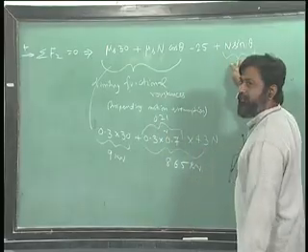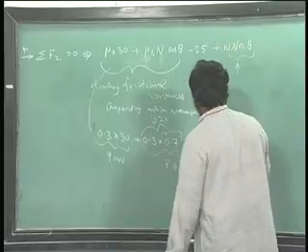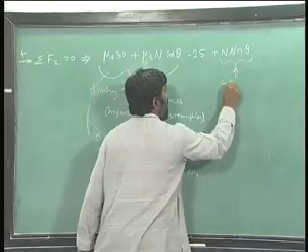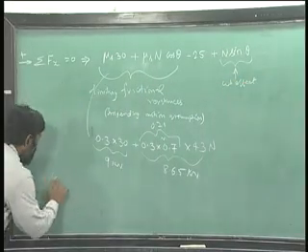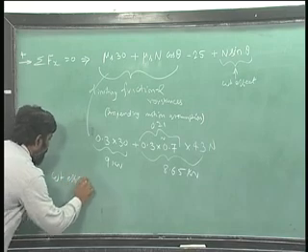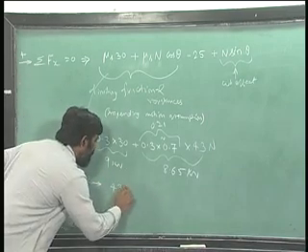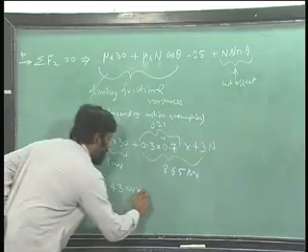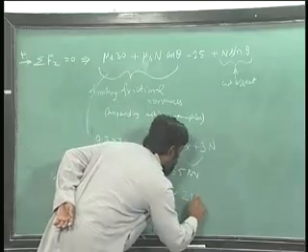What is the rough value of this? The n is around 43. So, let us say this is the weight effect, just to get an idea. It is 43 kilonewtons times sin 30, which is around 0.5, and that gives me around 21 kilonewtons.